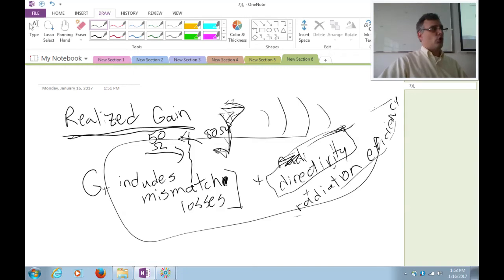In this class, if you're not given any electrical specifications about the circuit that antennas are connected to, you can assume that the mismatch losses are negligible. Thus, realized gain is the same as absolute gain. But you have enough savvy in this class that you can calculate both scenarios if that's the case.